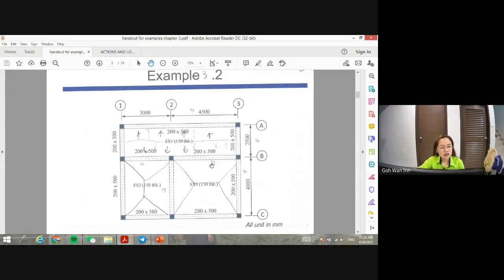So automatically here is Ly and Lx. Why you need to do this? Because remember when we want to use the table 1.9 for the case, we need to use the equation beta vx for Ly and beta vy for the Lx. It's 2 different values. Okay, if you get the wrong one, you get the incorrect answer.